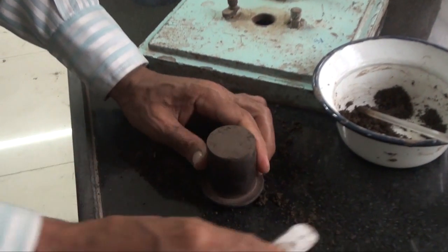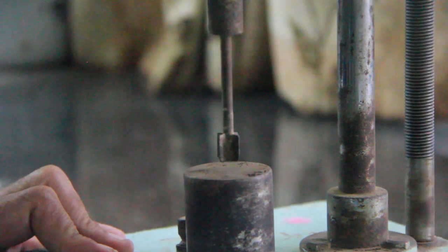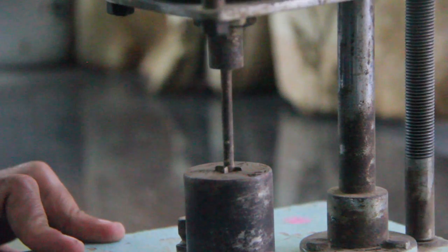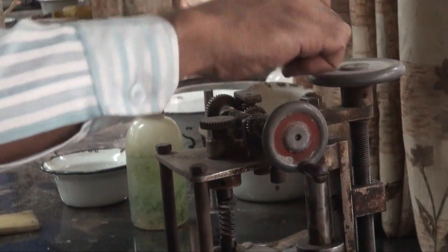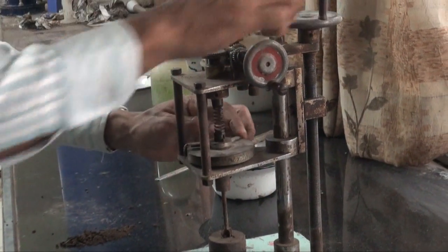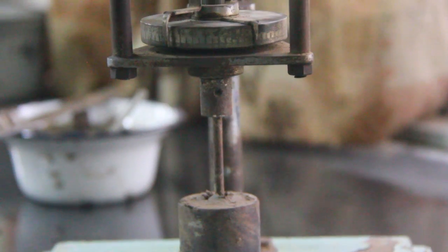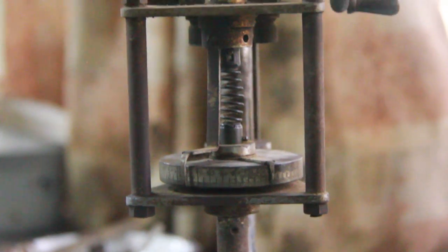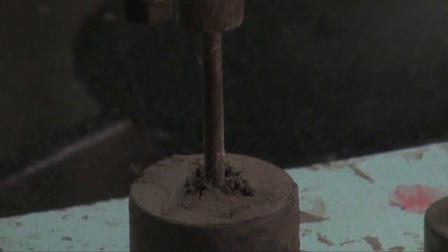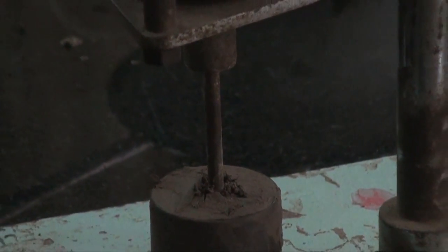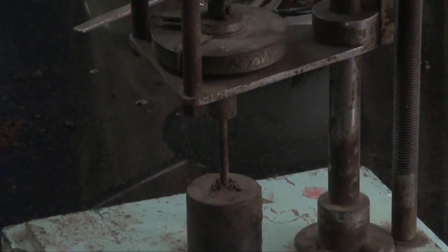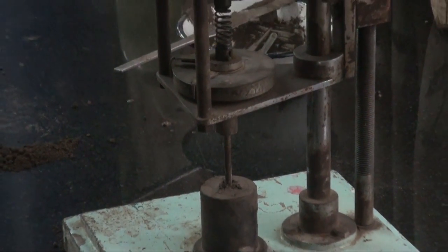The advantage is, it is the most appropriate method for saturated clays of soft to medium consistency. Imagine a soil sample which is too soft or with a very low shear strength to get it to the lab undisturbed. This kind of soil cannot be used for the tri-axial test. It is useful for soil which will not remain in a stable shape. In such cases, the vane shear test is the cheapest and the quickest method. Another example is that the sensitivity can also be measured by this test.